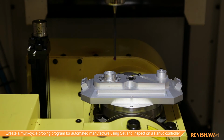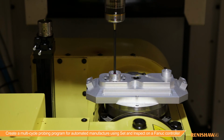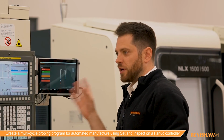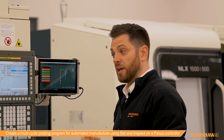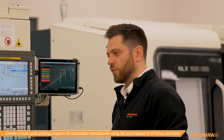Great, as easy as that. So what that's going to do now is come down, take a point on top, the point, yep. That's right. And then four points in there. Of course this is a self-contained program, so all we need to do is change one of the settings in here to make it a sub-program, and then you can call this from any cutting program that you have as part of your manufacturing process.